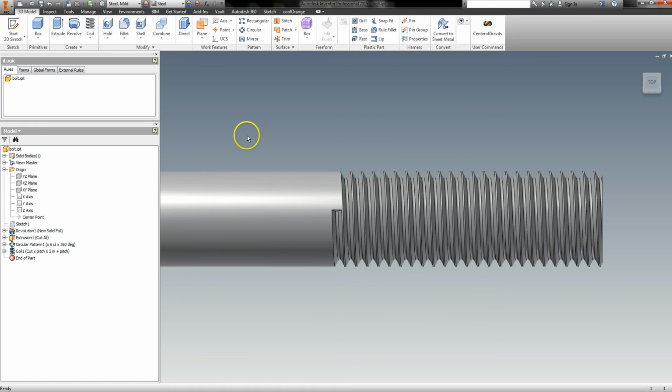So there are different ways the thread can end. It can taper, where the cutting tool is retracted as the material is still spinning, and you get a little bit more of a cut as the profile tapers out. You can have a relief groove, which I feel like is more common than anything else. It's a groove that's cut into the material that allows the tool to move into that space and then is retracted, to where as it moves into that space it no longer cuts any material. And I'm sure there may be others as well, but for this demonstration, what I'd like to show you is the relief groove.